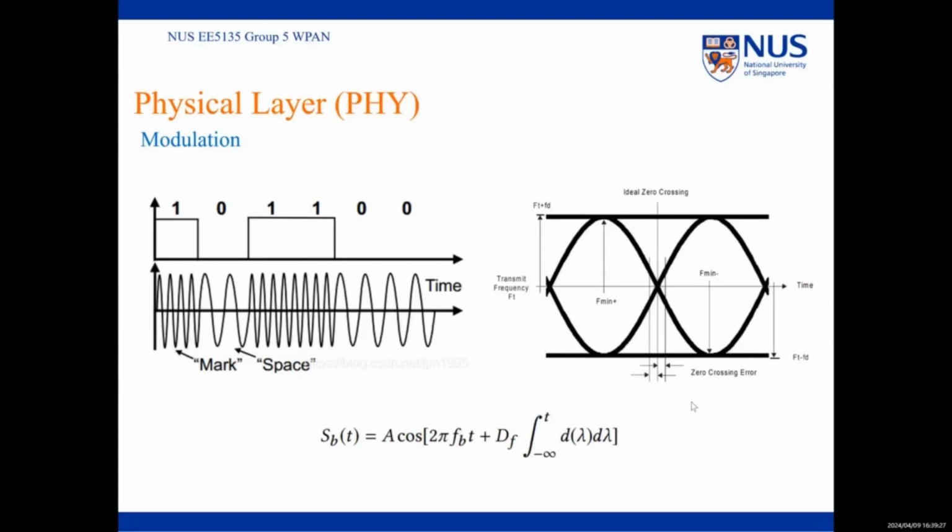This PSK variant allows reaching a raw data rate of up to 2 Mbps. The second is the 8-phase differential phase shift keying, which we call 8DPSK, used under favorable link conditions to support raw data rates of up to 3 Mbps.